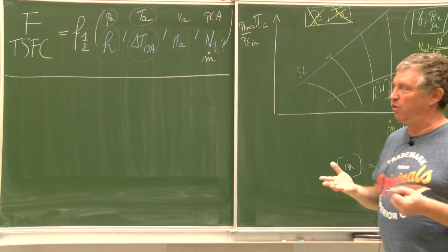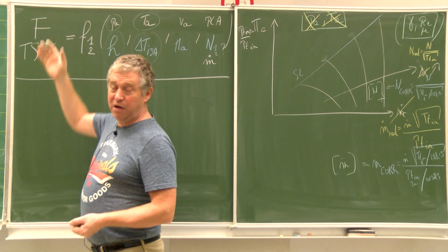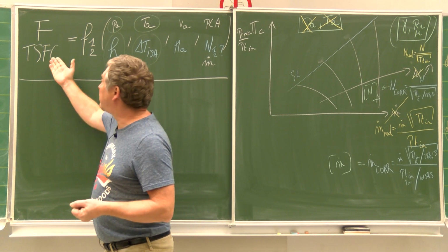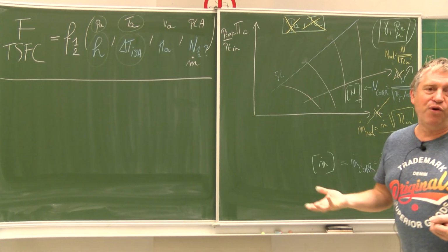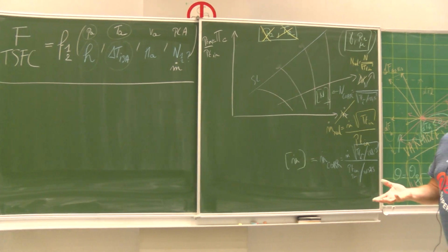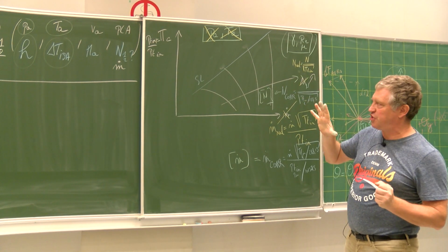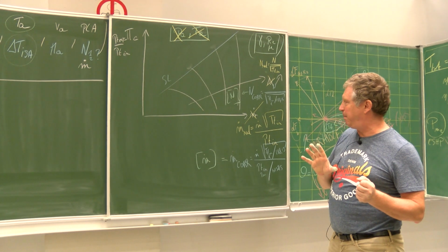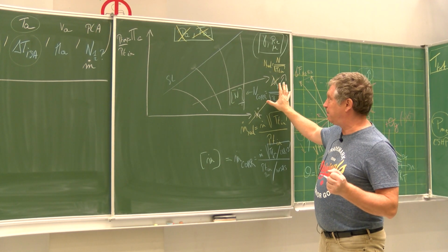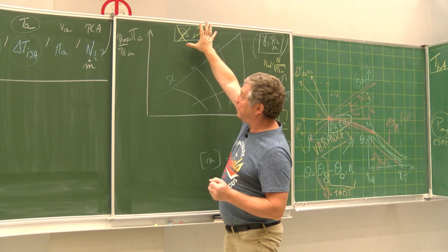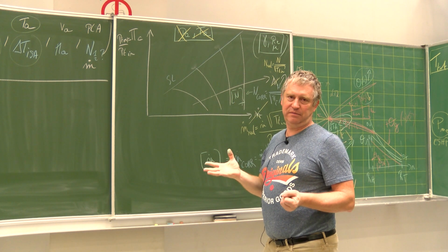You can measure all these parameters physically. You can also measure the thrust with a load sensor. You can measure the TSFC with a load sensor and a flow meter to measure the fuel flow. So these are physical parameters, and we switch from the world of the physical parameters to the world of the reduced or corrected parameters without taking with us the influence of the atmosphere.